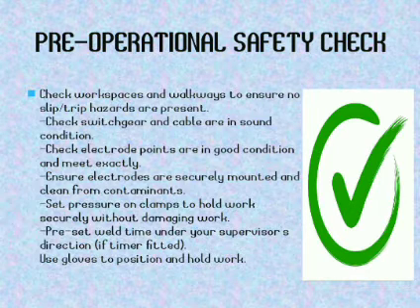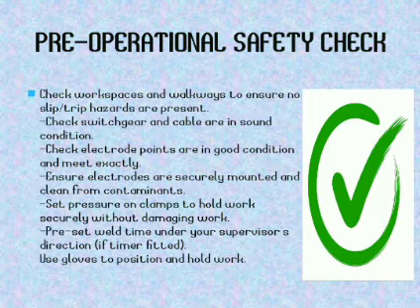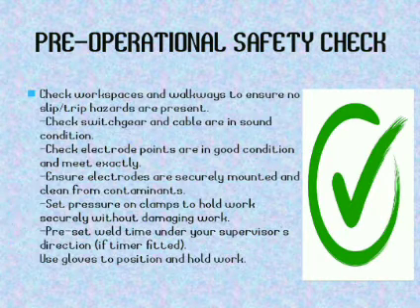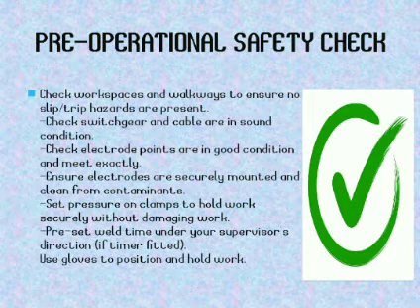Ensure electrodes are securely mounted and clean from contaminants. Also set pressure and clamps to hold work securely without damaging it. Preset weld time under your supervisor's direction if a timer is fitted, and also use gloves to position and hold work.